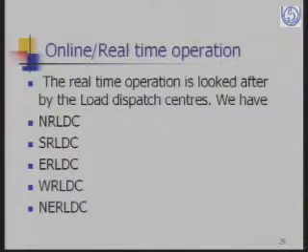Why, madam, are these called load dispatch centers? Yes, why are they called load dispatch centers? They schedule. For our learner friends, kindly explain that a little bit. They are called load dispatch centers because they see which generation, which transmission line is to be put on, which is to be put off, or which generator is to be put into the system to supply the power. So they do the load dispatching, they do the scheduling of the generation as well as the load. That is why they are called load dispatch centers.